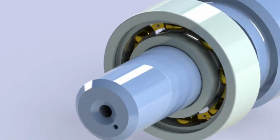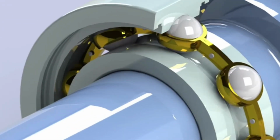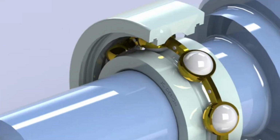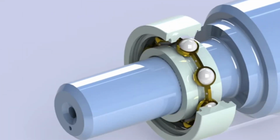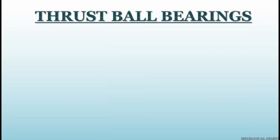First you should know what radial and thrust load are. Radial bearings support the force that is applied vertically to the shaft. Thrust bearings support a force applied in the same direction as the shaft. Don't be confused, thrust means axial load, front and back movement. We'll see the types of thrust ball bearing. There are 2 types available.